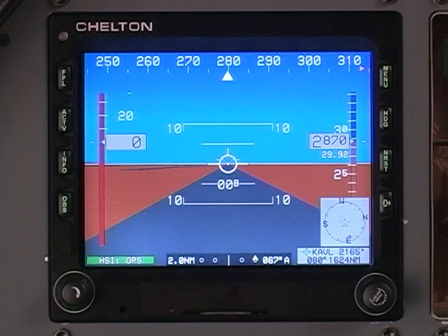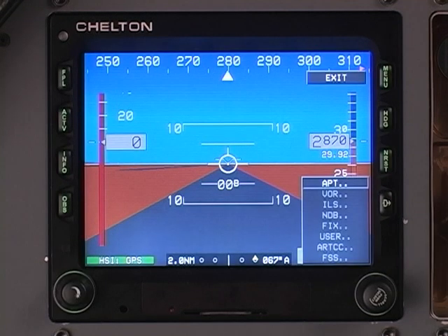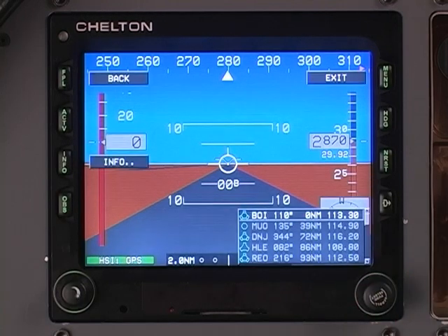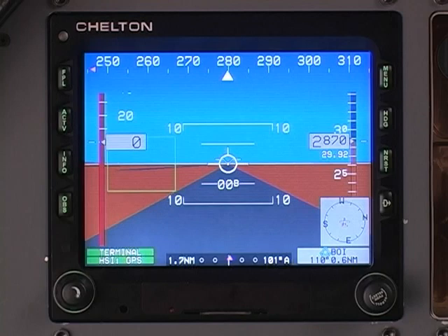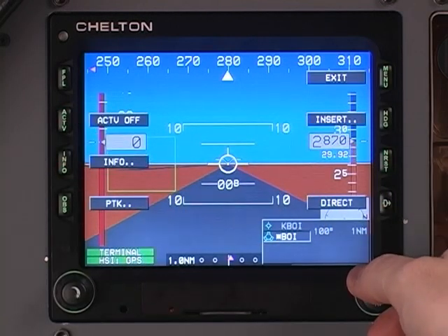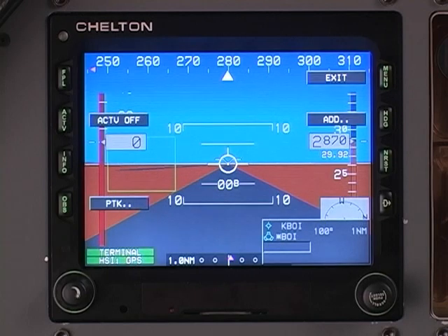Since the Boise Airport is not part of Victor 253, we will have to start with the nearest VOR, or fix on the airway. In this case, the Boise VOR is located on the airport, so we enter that as our first waypoint. Push the nearest button and use the control knob to choose VOR, then BOI. Now, push the Active button and scroll to the empty space after BOI and choose the Add button.